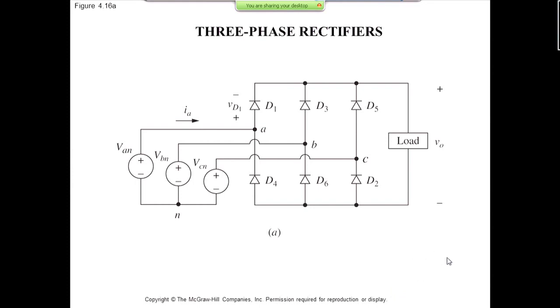So we are going to start talking about three-phase rectifiers. The first question is, why three-phase? What is wrong with single-phase? The answer would be, whenever you want to consume higher amounts of power, you want to consume this load in a three-phase balanced approach instead of a single-phase approach, because otherwise the power utility people are going to have a hard time balancing out their load.